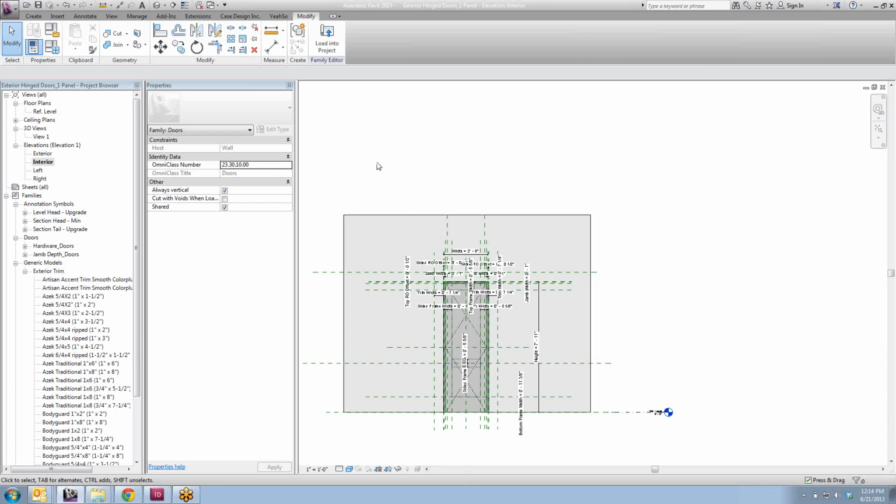What is the trim condition for interior doors, or what are the trim options for interior doors? Well, really, there's only one. The pine, I think, probably just pine trim. But in certain cases, like when you have a connector, when you have a doubled wall, the jamb size doesn't make sense to have it like 10 inches long or whatever, but you would have an extra long drywall return. But the trim on one side of that door would be offset from wherever that jamb is. You know what I mean?